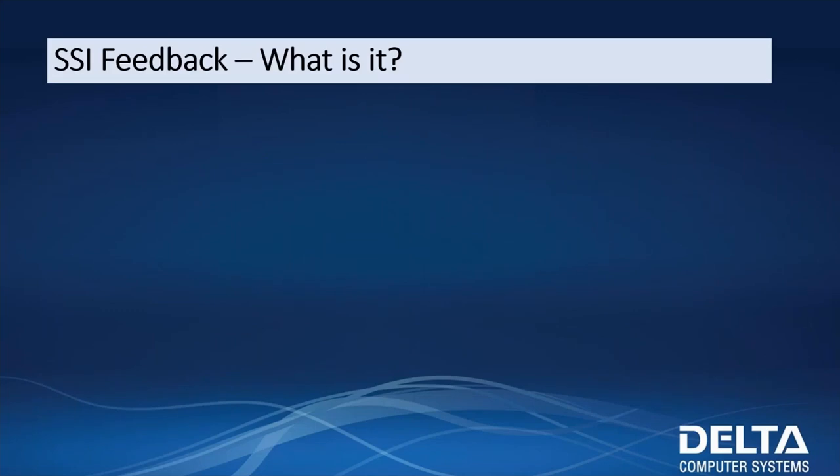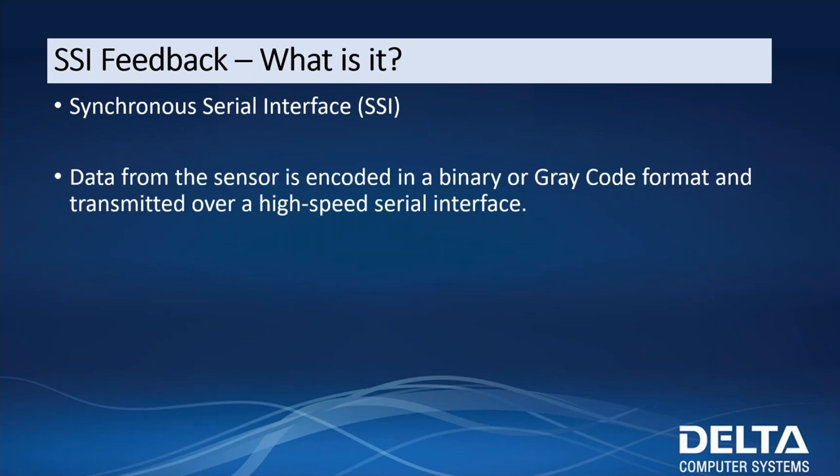So let's talk a little bit about SSI feedback. What is SSI feedback? Well, SSI stands for synchronous serial interface. Data from the sensor is encoded in a binary or gray code format, and it's transmitted over a high-speed serial interface.